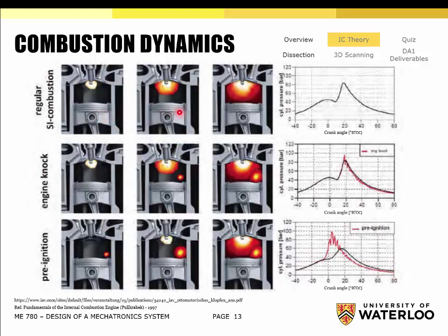Just ignore the fact that the piston in all of these diagrams is in the same position, okay? So we ignite the mixture, so we create this little kernel of burnt gas, okay? And it starts to expand in this hemispherical shape. So this is image 1, this is image 2, and this is image 3, until you fully sweep the entire cylinder, okay? And it's going to burn all of the gases within the cylinder, okay?